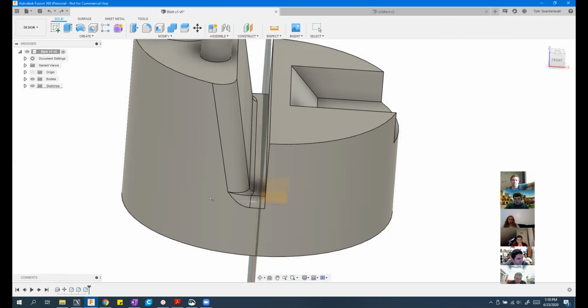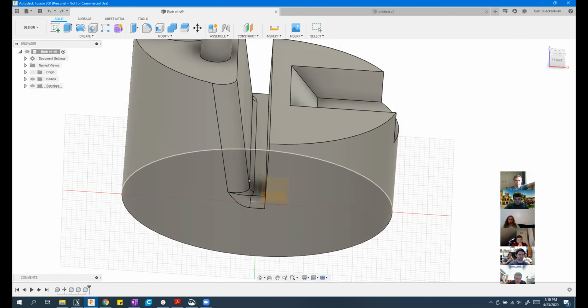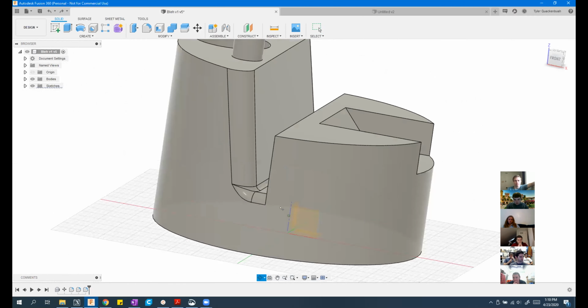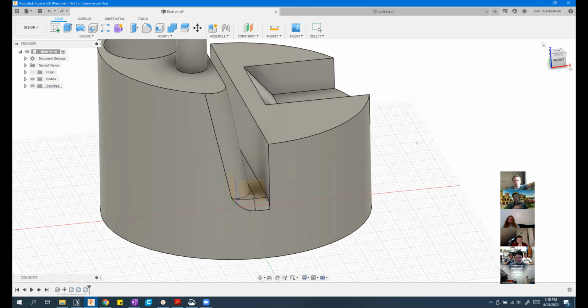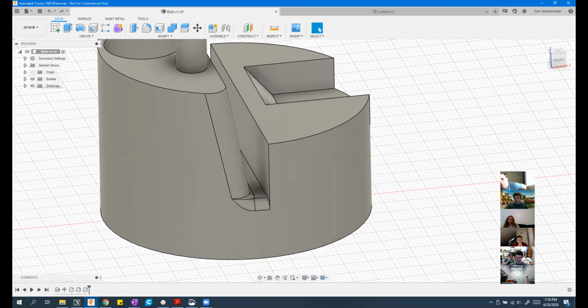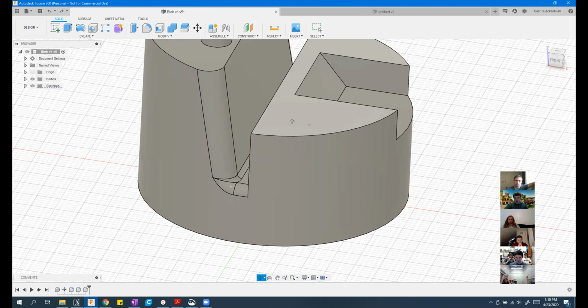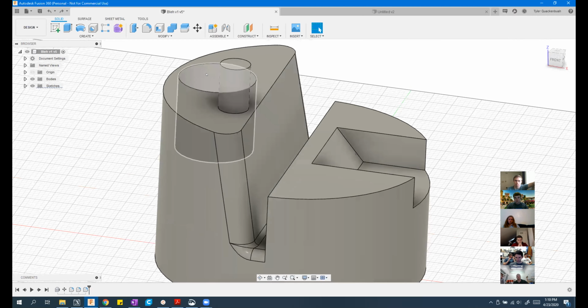But basically the concept is you take a sphere and you bust up your model and then you fix it by deleting that face. And usually Fusion can recover geometry and it can make edges square again when there's a bunch of weird fillets intersecting, and you can go in and put normal fillets on them. If you want to learn more about that, watch the direct editing one.